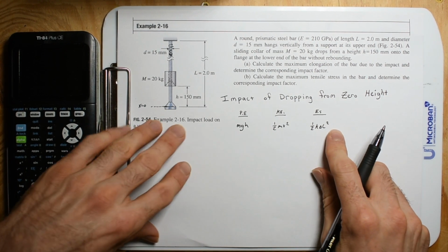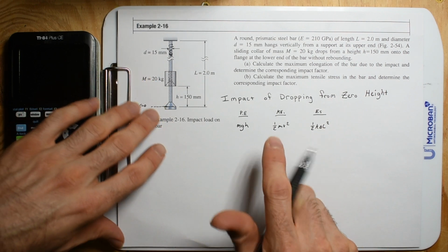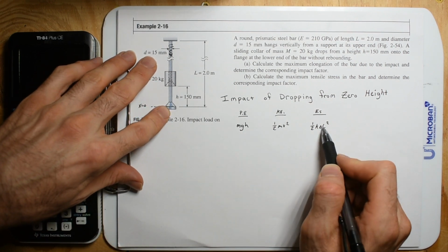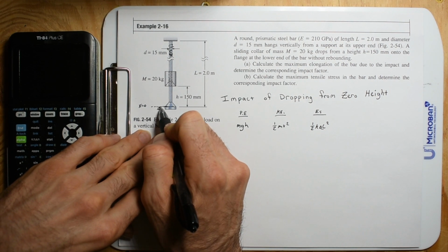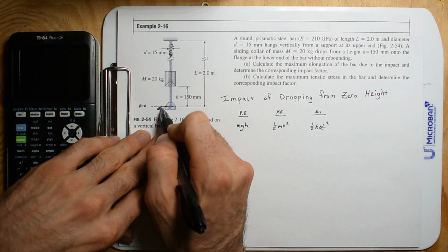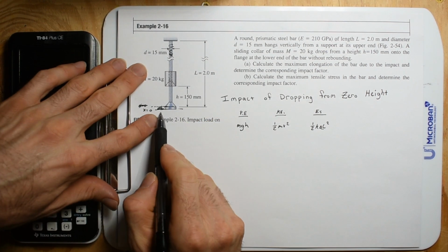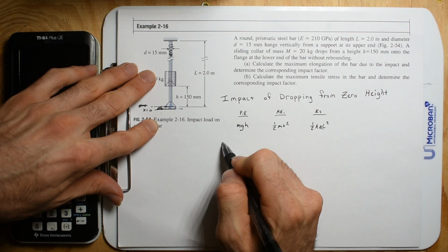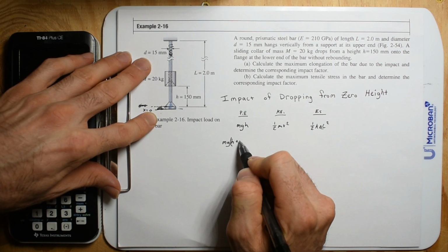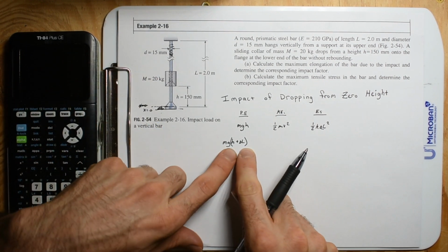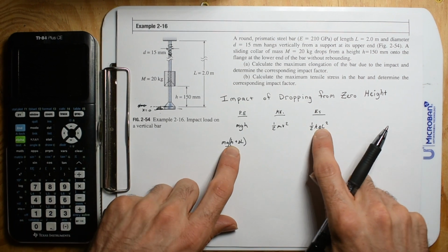All right, sweet. But this isn't exactly what happens, because if we do have a change in length, well, then our datum is going to be some sort of delta L change in length, and so we have to take the datum from there. That's if we're talking about potential energy, that would have to be our datum. So our mgh would be mg times h plus change in length, and this is how they have it written in the textbooks. And then you can say these two things are equal.